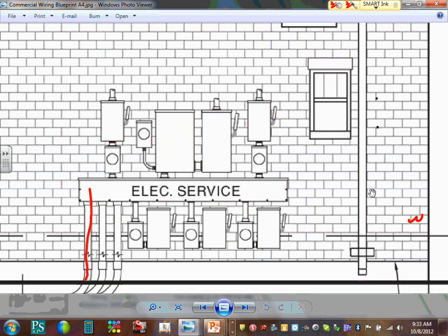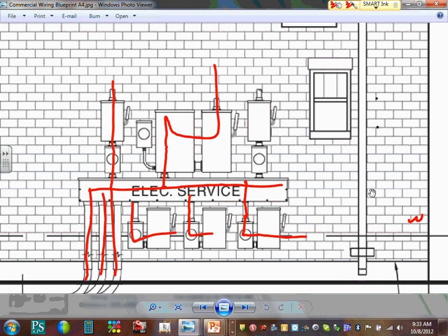So here's my power coming in, all the 3 phases, and I'm tapping these conductors in and out for each one of them. Can you guys see that? In every meter and out. And the same thing here, in and out, and the same thing here, in and out. For disconnect, this is the CT cabinet, and the same thing in and out. How many disconnects do we have? 6 disconnects? 1, 2, 3, 4, 5, 6 grouped in one location.